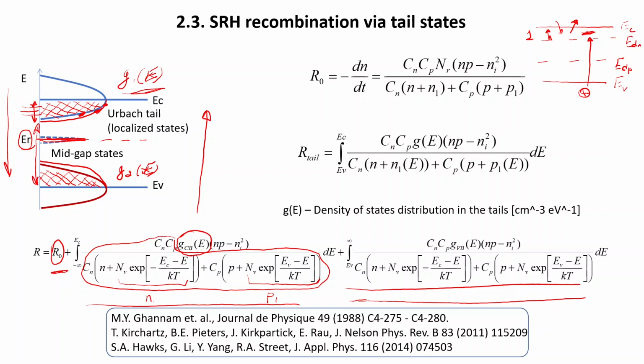There is a parameter which defines how fast electrons can move in an external electric field. There is the mobility of charge carriers, mu. We will discuss it a bit further, but I'm sure you heard about this characteristic previously. So the mobility of charge carriers will be negatively impacted, because part of their life, they have this recombination life, their life is limited. They don't live forever. But part of their life, instead of moving and being extracted from the device, they will be trapped and will not participate in charge transport.